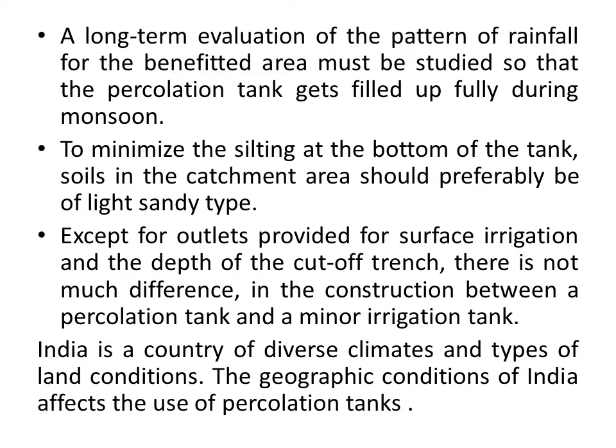Except for outlets provided for surface irrigation and the depth of cut and the depth of the cutoff trench, there is not much difference in the construction between a percolation tank and a minor irrigation tank. So there are similarities between the percolation tank and the minor irrigation tank for construction purposes, except that outlets are provided for the minor irrigation tank and not for the percolation tank, and there is also a difference in the depth of the cutoff trenches.